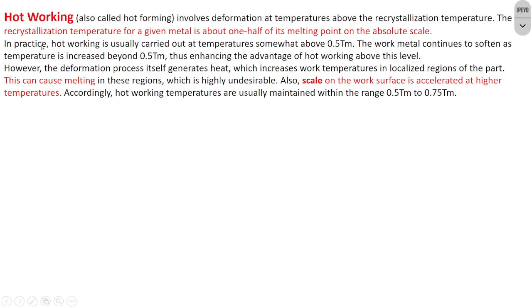If the material is very hot, it can react much more quickly with the surrounding atmospheric air, and over the surface, unfortunately, we have scale. Scale means a layer of oxides. Okay, scale on the work surface is accelerated at higher temperature.